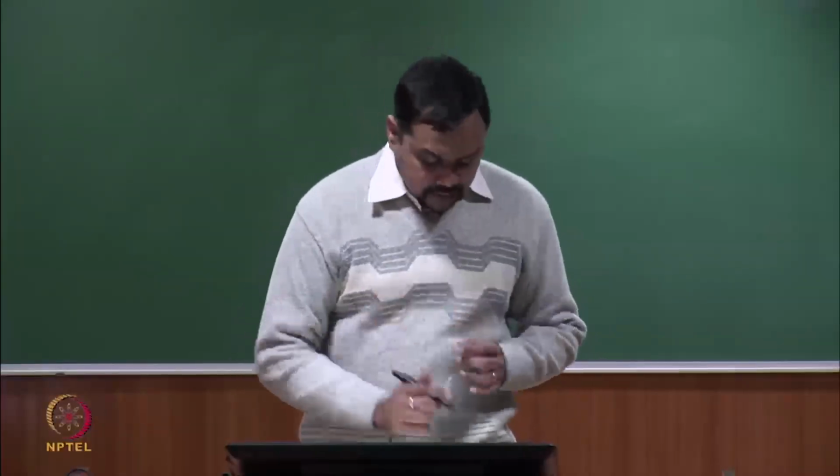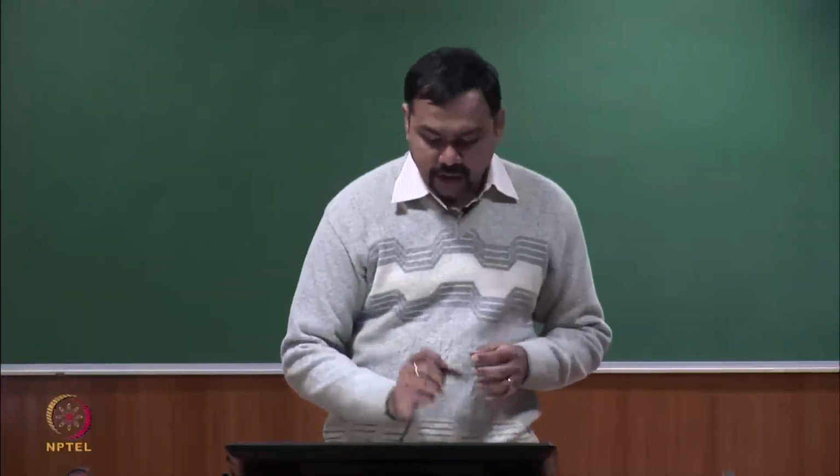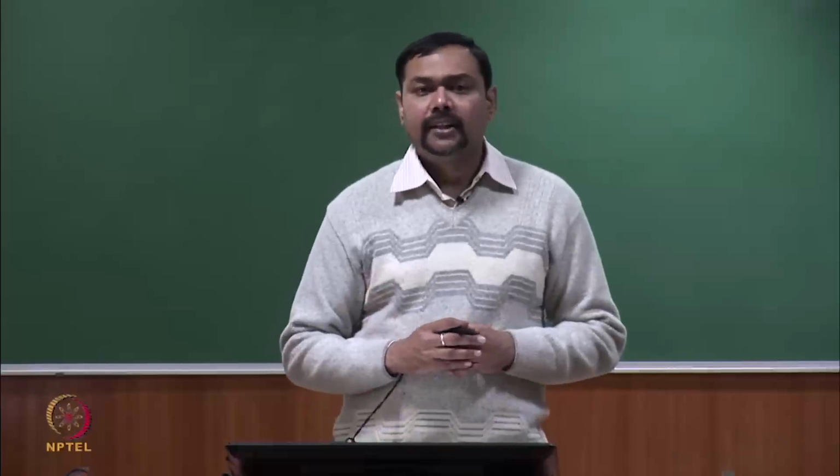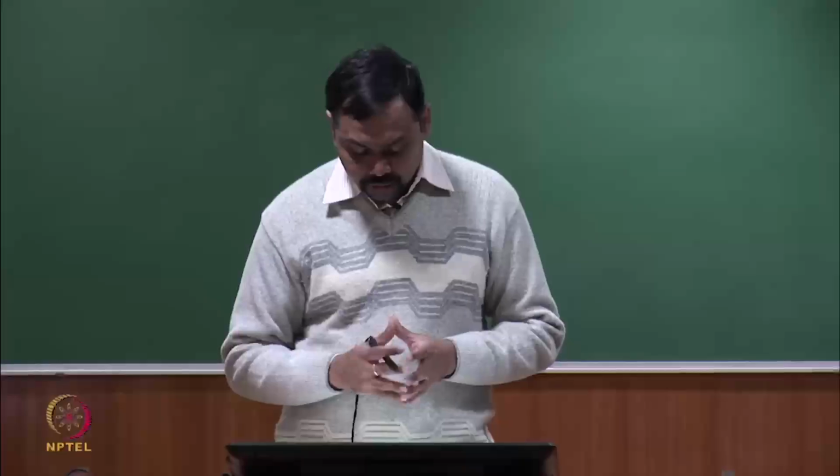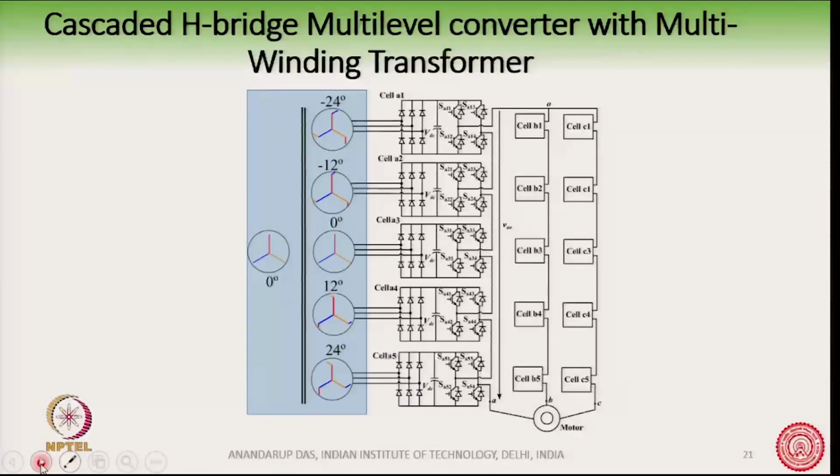Now, before I proceed on the zigzag transformer, let me show you how the zigzag transformers or these multipulse transformers can be used in, suppose, a cascaded H-bridge converter. So, we had seen that cascaded H-bridge converters required a large number of isolated DC sources, isolated DC sources here.